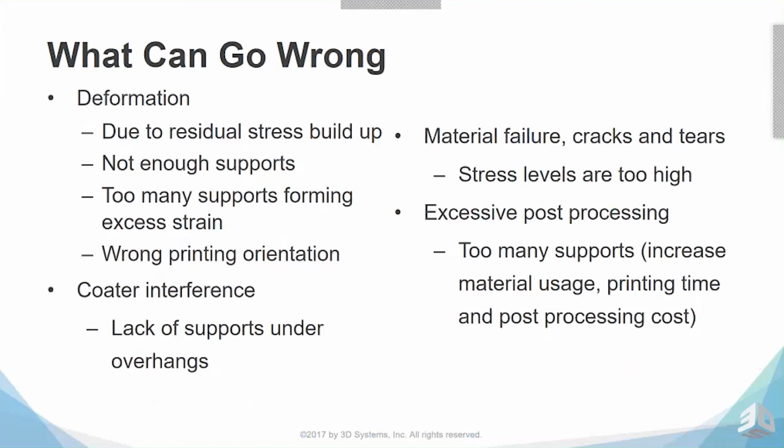Coater interference. So this is your coater that's going to distribute the powder across your bed. If you have some parts that are swelling up or deforming and interfering with that recoating system, that can really give you some cascading failures and maybe even crash your build.